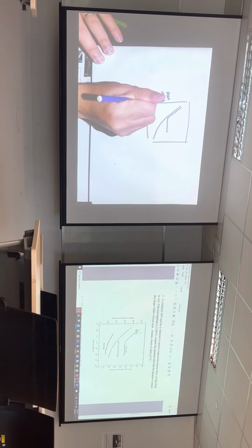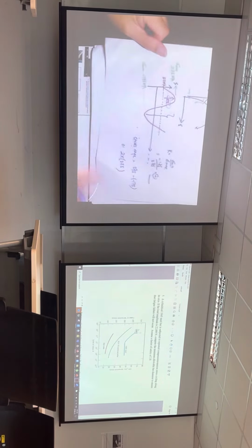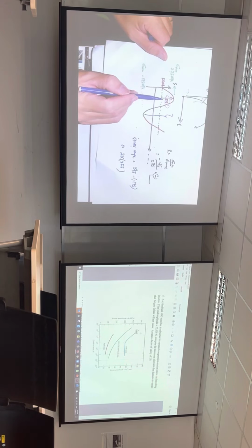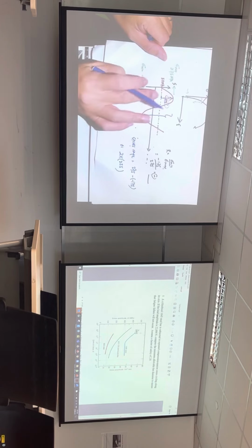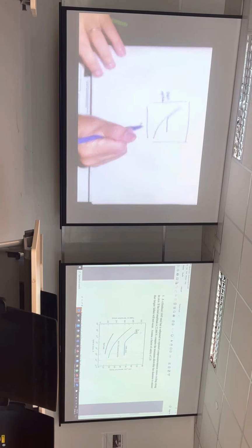Just in case you forgot what is stress amplitude. The stress amplitude is this value from here: max minus min, times half. It's not from here to here, the 225 value. So about the mean, basically on each side, it is 225. So just to give you an example, the stress is being plotted as the stress amplitude versus the cycle.